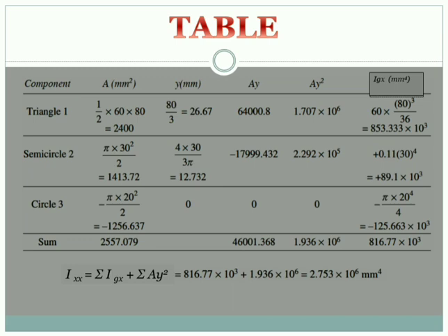Then third component is a circle. In area itself as well as in moment of inertia, we have to take a negative sign because it is cut out. So with a negative sign, when we start, the area of the circle is pi r square. Okay, so the area formula is pi r square, that by 2 while copy pasting from the top has come. Okay, take the right formula.